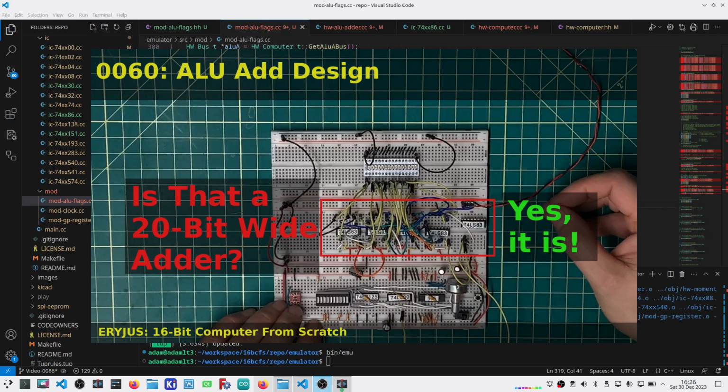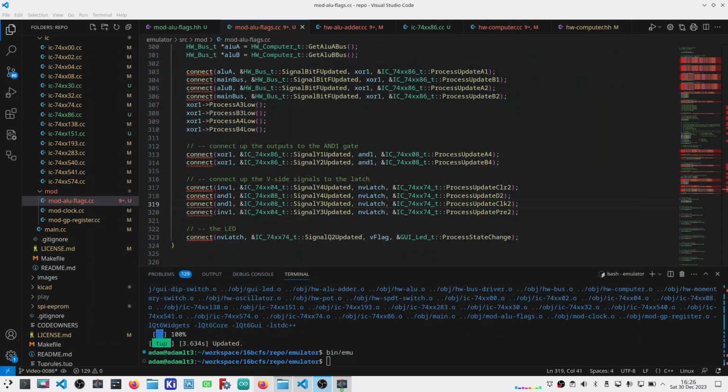So I believe that even though this is one gate deeper in the ALU, it's actually going to be a faster response time. It shortens that propagation delay for sure, which was one of my problems. So that said, this is what I have managed to come up with.